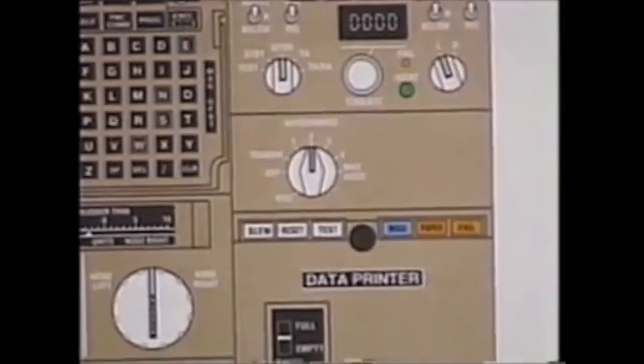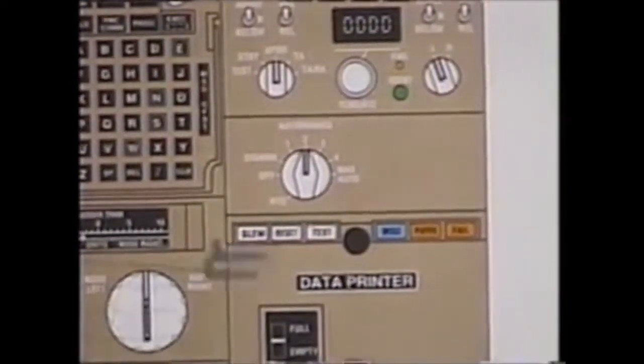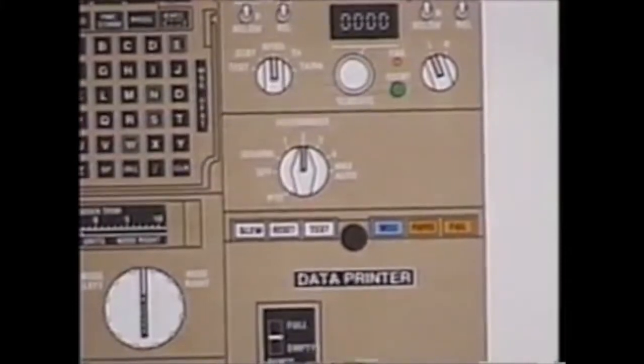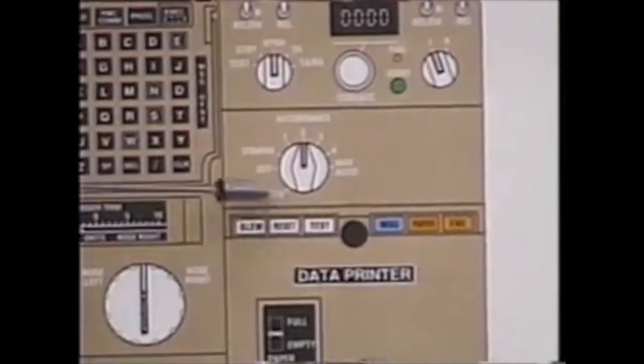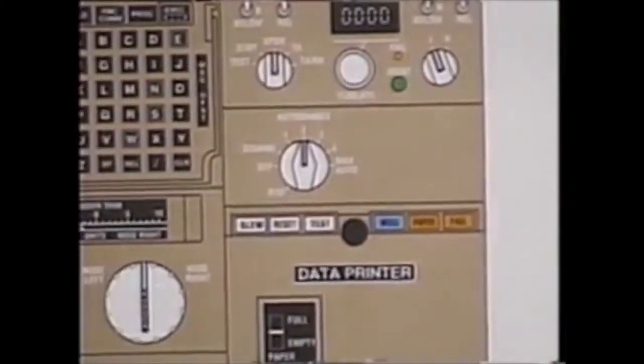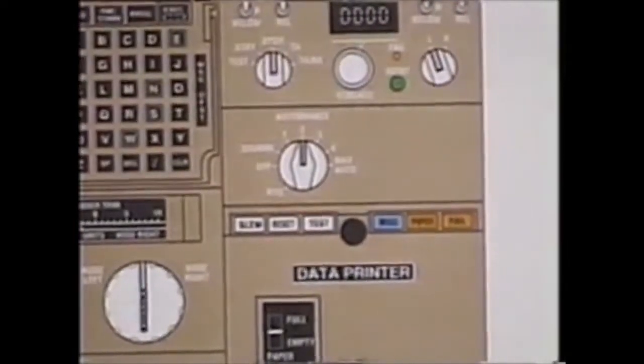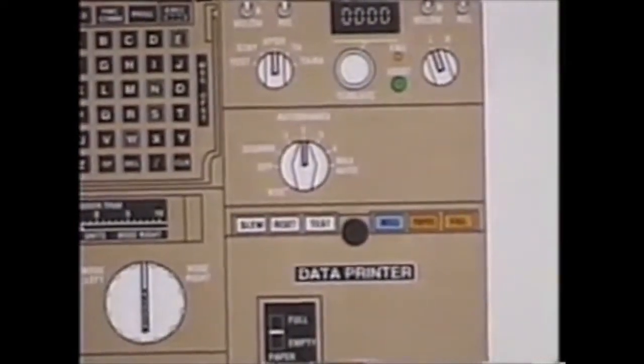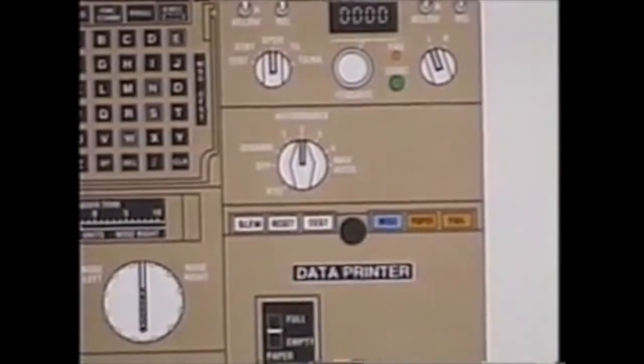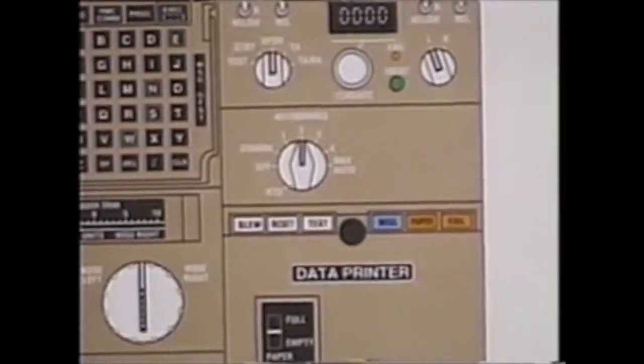Our discussion now will move to the aft right corner of the center aisle stand with our auto brakes. Auto brakes, we can use this system for takeoff by selecting RTO. RTO is selected during the cockpit setup by the captain. RTO is armed whenever the ground speed is greater than 85 knots. RTO is activated by closing the throttles.